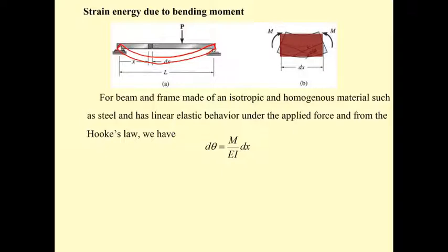And this portion of the beam that used to be straight is going to bend into a shape like this one. As you may know, you may cut this one, and you can determine the reaction here and here, and when you cut here, this is going to produce the moment M. So this moment is the one that causes the deformation of the beam.